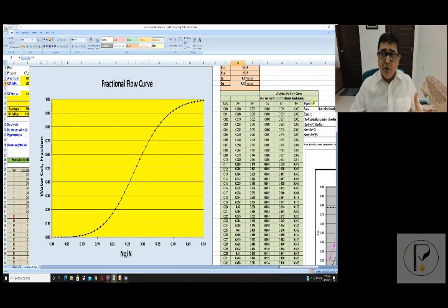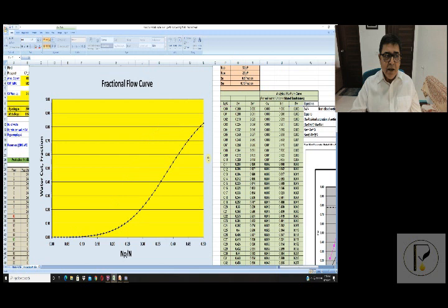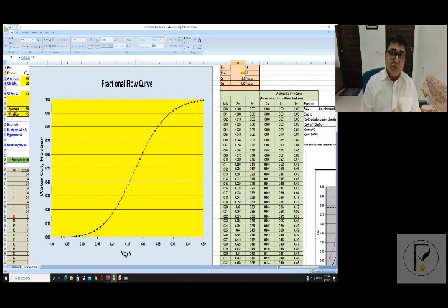Now, what next? After polymer, no one gets satisfied at the end of the day by achieving 37% at 90. So, well, some operator can think of doing ASP and bringing down the residual oil saturation further, shifting the fractional flow curve subsequently to the right, adding some more recovery, around 5 to 10% more over polymer. So you see the fun, how your processes are linked to fractional flow. So this is one school of thought.